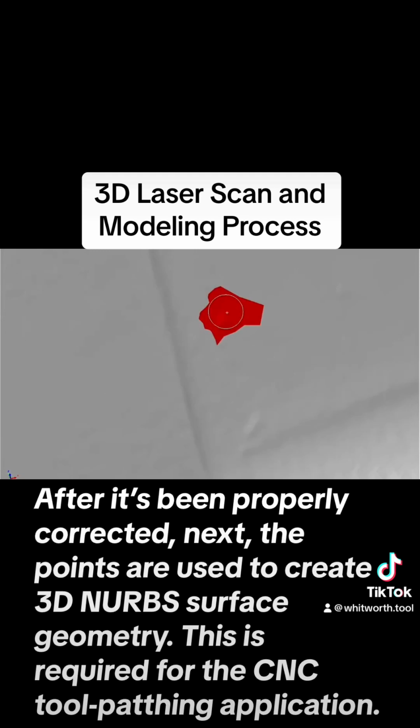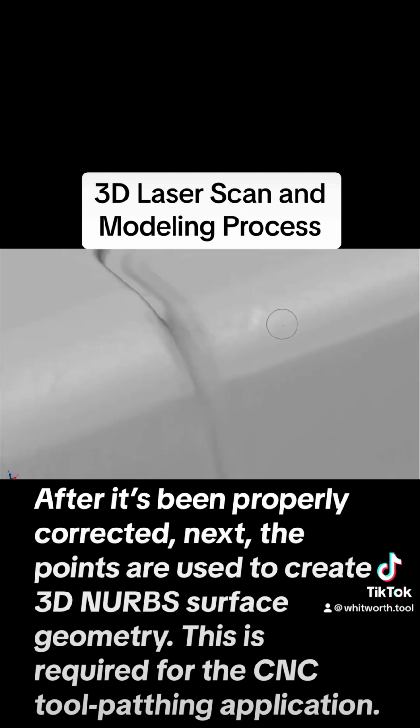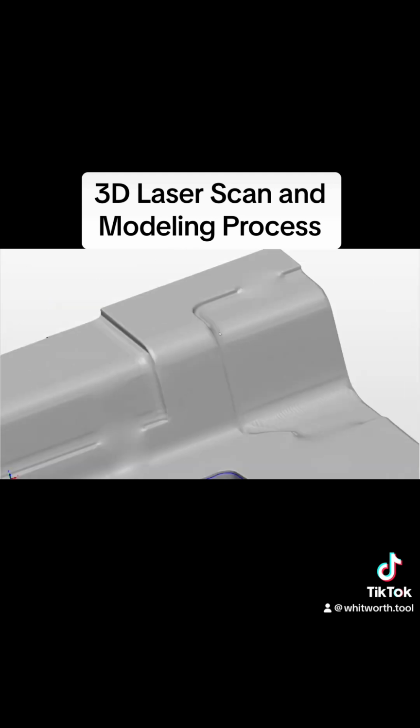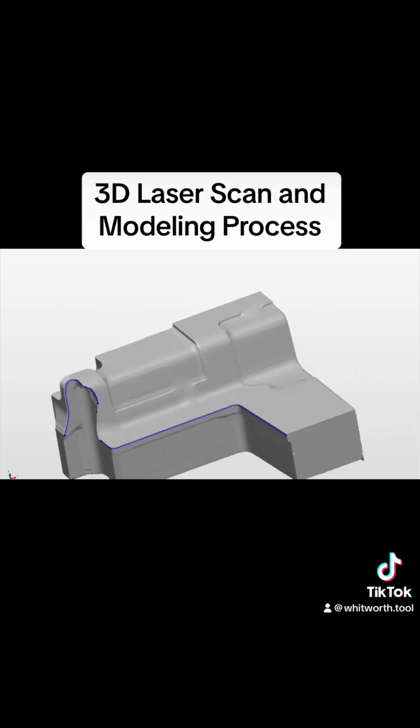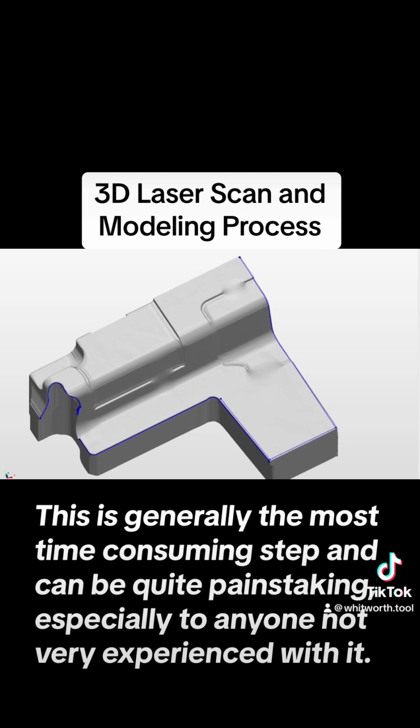After it's been properly corrected, next, the points are used to create 3D NURBS surface geometry. This is required for the CNC tool pathing application. This is generally the most time-consuming step and can be quite painstaking, especially to anyone not very experienced with it.